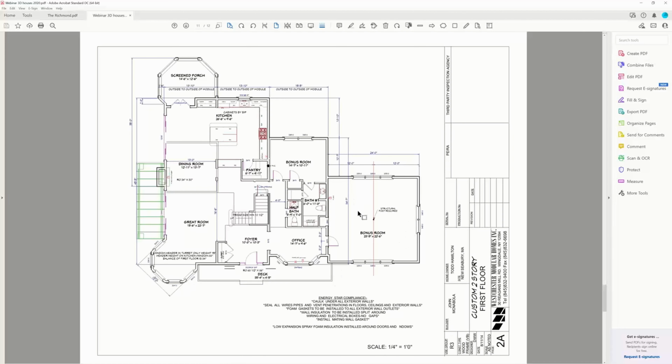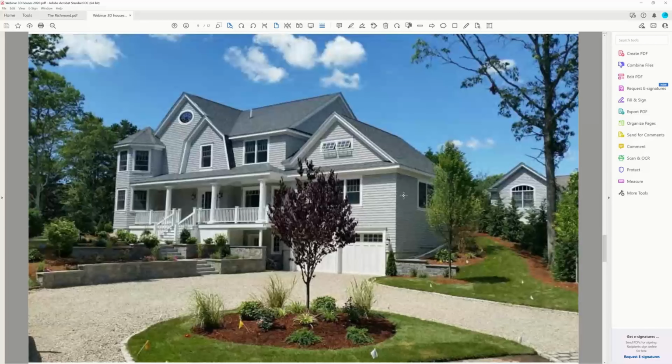And this bonus room, which was just open space over the basement level garage, we decided not to build as modules because we could have, but we couldn't offer the value there. So we did that as panelized walls. And then the roof of that garage we did as pre-assembled roofs. They were built in two halves, shingled in the factory, off the production line, and brought down.